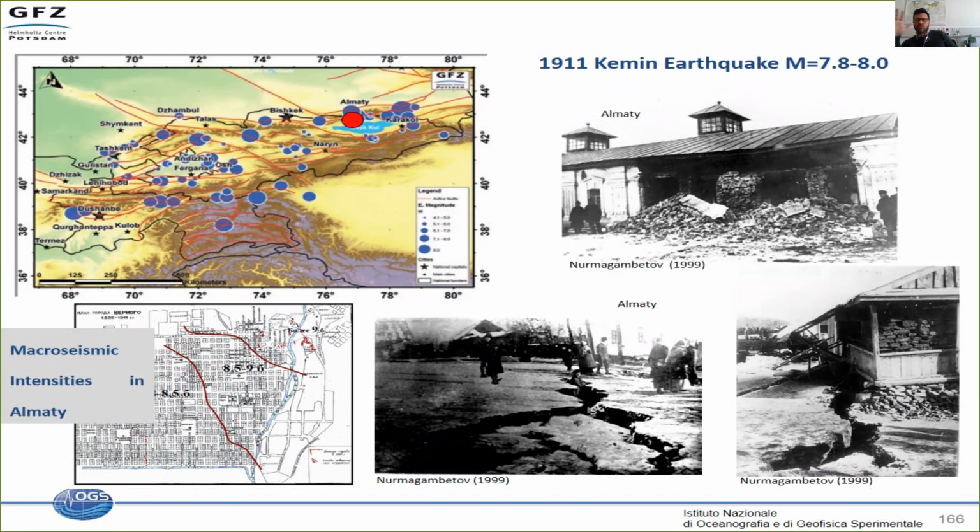In this case, as I was mentioning before, this earthquake happened in January, while the earlier earthquake was in July. We assume, and we made some numerical simulation, that in January you have 1 meter of frozen layer. In June, July, it would have been possible for the pore pressure to dissipate, because you also have some gravel material and sand. In January, it was not possible because the frozen layer was like a seal.